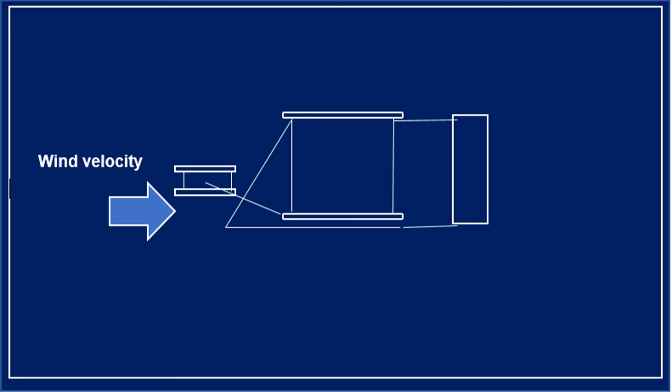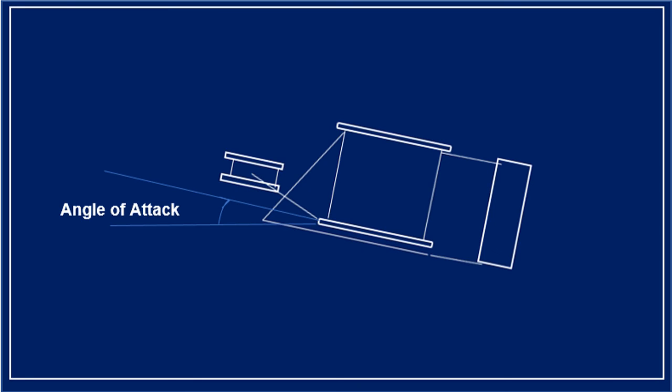The other thing, but of course this comes with a downside, is that we have calculated the lift at an angle of attack of 0 degrees. What I mean is basically that the angle of the wing, as opposed to the flow, is 0 degrees. When an airplane takes off, an angle also exists between the wind and the wing. They could have done something similar, and that generates a large amount of lift, but reduces the amount of speed. So the speed in effect would also be lower. So technically you could fly at a lower speed but have a higher lift.